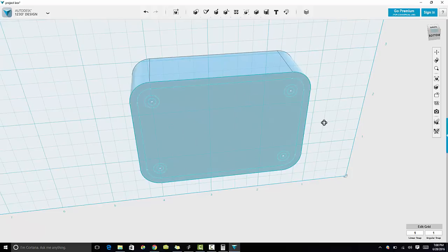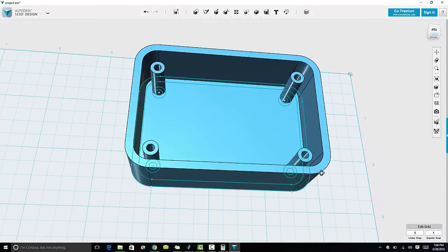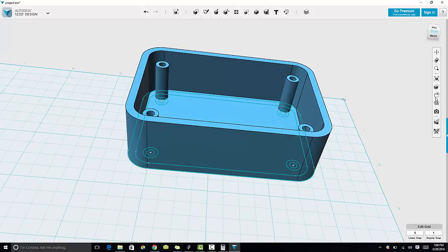And that's another number that I chose for a good reason, and I will explain. The reason I chose that number is the type of lid that we are going to make is going to have a recess in the center of it. Basically what I mean by that is the lid is actually going to go a little bit inside of the case.